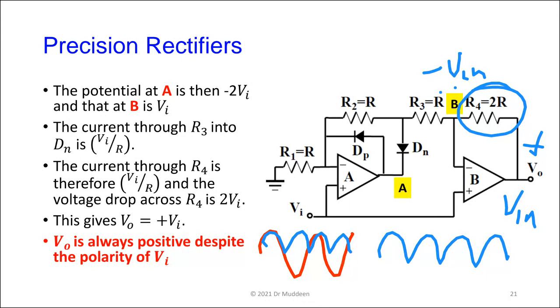The op amp works, as I mentioned, right here. Once the op amp turns on, the op amp forces the 2 inputs to be at the same voltage level, and to force the 2 inputs to be at the same level, it controls the output. That's what the feedback is doing.